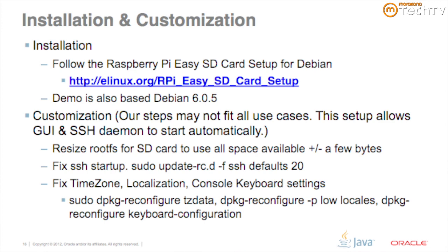So one of the first steps that I usually do, when you get this card, I've gone onto the website and researched. Most people stick their card into the device, they DD it, and then they put it into the machine. They're like, I only have 120 meg left, I can't do anything with this, and they had a 4 gig card to start from. So basically the first step is just to resize the SD card.